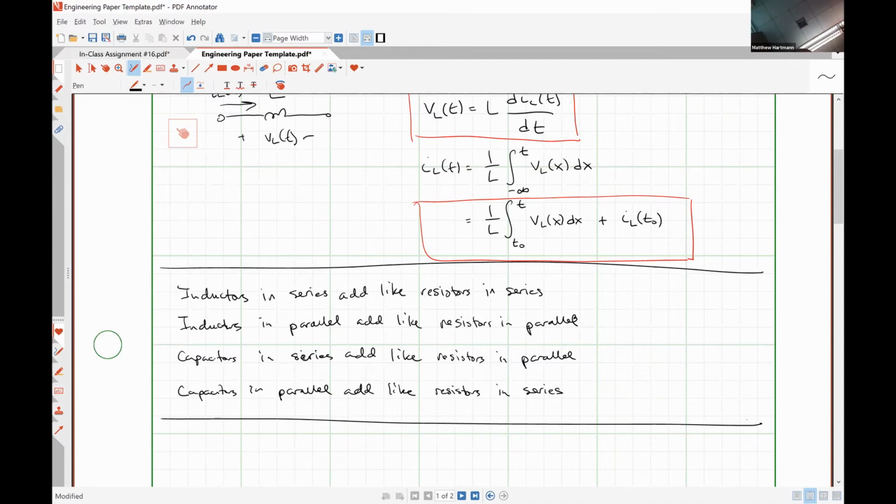So it's not forgetting that the time constant for an RL circuit is L over R, or the time constant for an RC circuit is RC. It's fundamentally computing that value for REQ where I see the most errors being made. So the equivalent resistance at 0 minus, that's the Thevenin resistance essentially, right? It's the same resistance either way. It's just we have to look at it during the transient condition for it to be part of our time constant. So for instance, let's look at the winter exam, problem 26 through 30,